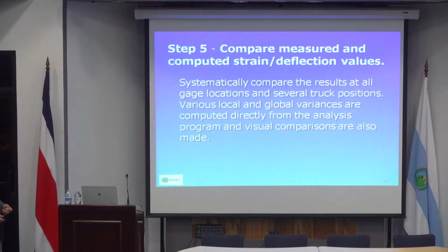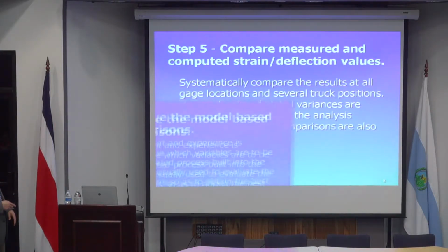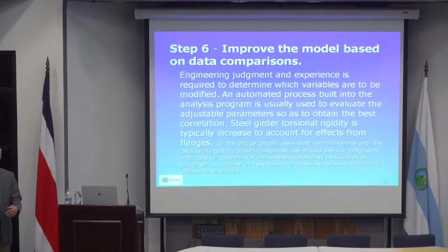Then, once you have the best fit, compare the test data and just change these characteristics, and then you get a best-fit situation for strains and deflections. Then just use that model to calculate the bending moments and shear forces of these girders and so on, and that will give you more realistic results.